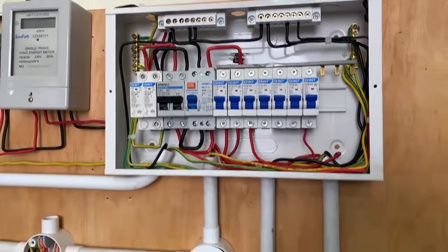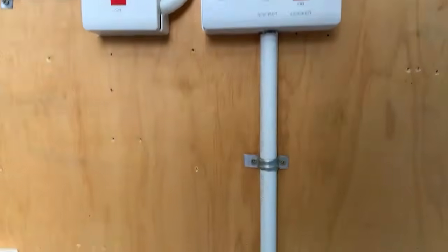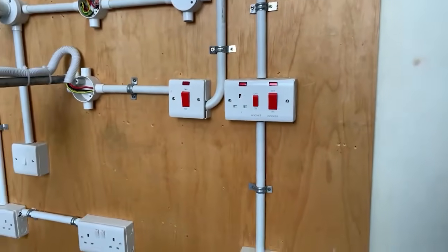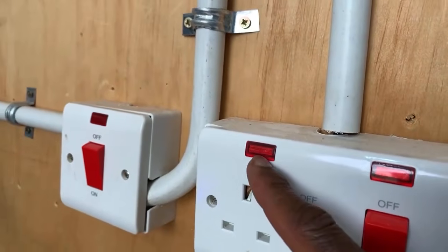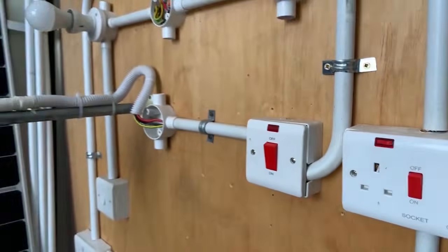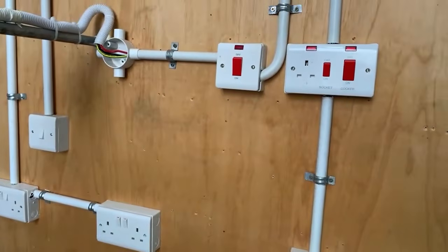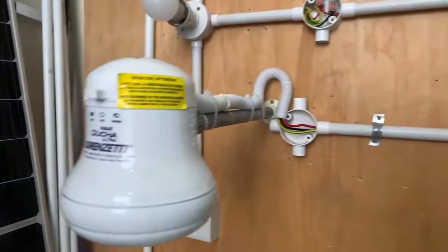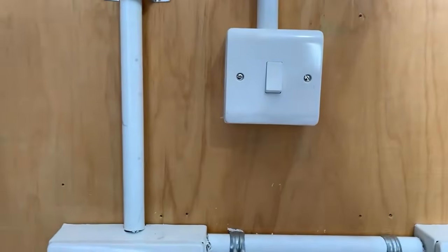As you can see, there are multiple connections. These connections serve various circuits, like we have here the cooker. Assuming that the cooker is not receiving sufficient power, there's going to be a problem. Sometimes you'll find that this light here is dim or really flickering, that you can see with naked eyes. Same as this one for an instant shower head. This is a heater. Heating circuits face a lot of issues, especially if the installation was not done by a qualified person or a careful person who was definitely concerned about tight electrical connections.